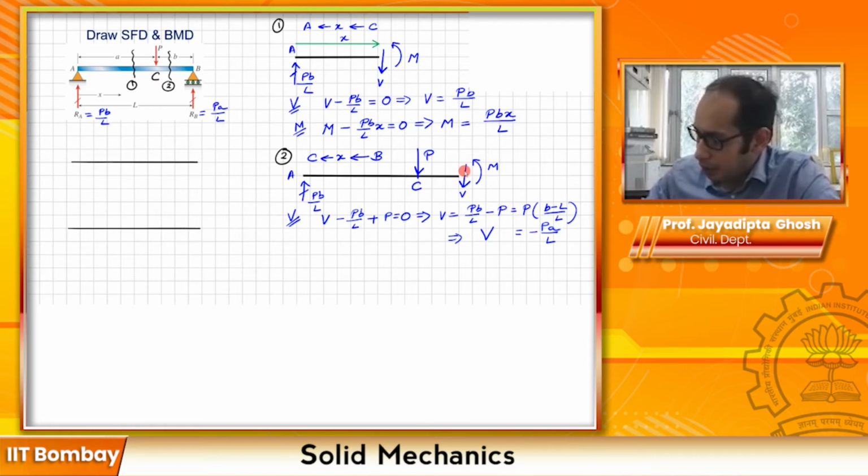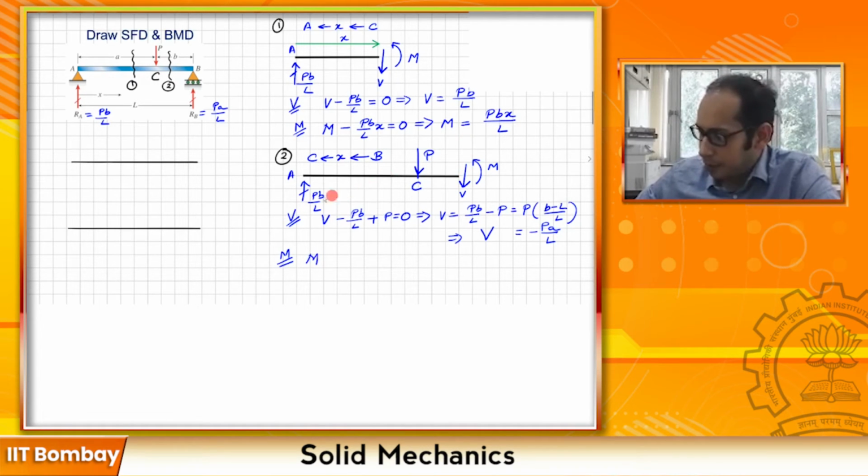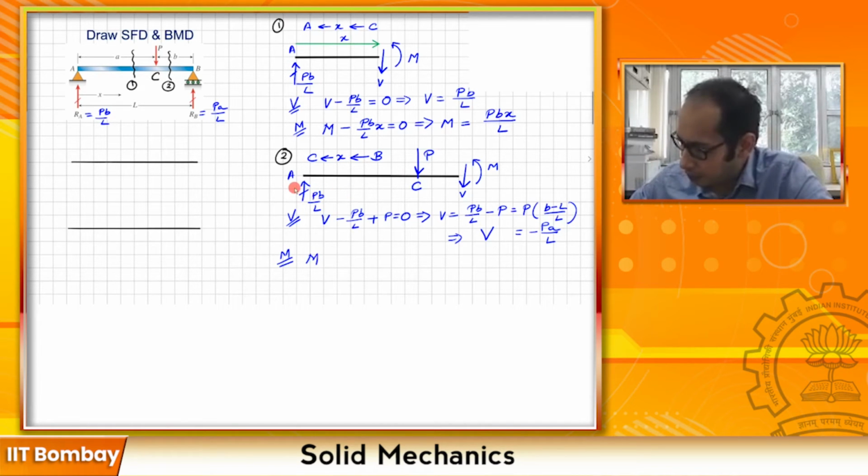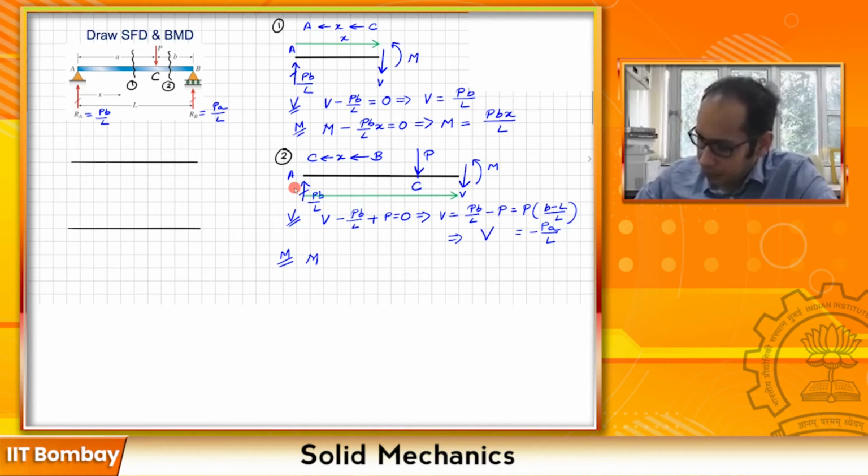And the next one, so we have calculated the expressions for the shear. So let's go ahead and write the expression for the bending moment now. Again, taking moment of the forces about this particular point. Again, I have M and I have this force here. Now remember, this distance again is x, because I'm taking x all the way from left to the right. So let's just mark this one. This is x over here.